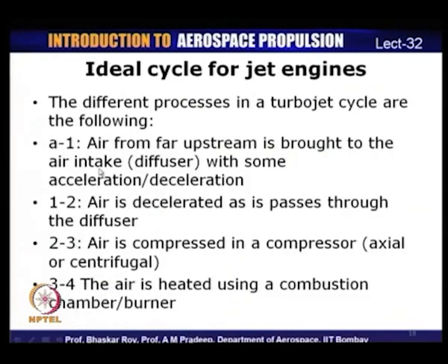So, the different processes, as I mentioned: the first process is A to 1, in which air from far upstream is brought to the diffuser entry with either some acceleration or sometimes even deceleration, and process 1 to 2 is the intake or the diffuser, where air is essentially decelerated as it passes through the diffuser. Process 2-3 is the compression process. In the compressor, which could be either an axial compressor or a centrifugal compressor, air is compressed. Process 3-4 is the heat addition process. Air is heated during this combustion process in the combustion chamber.